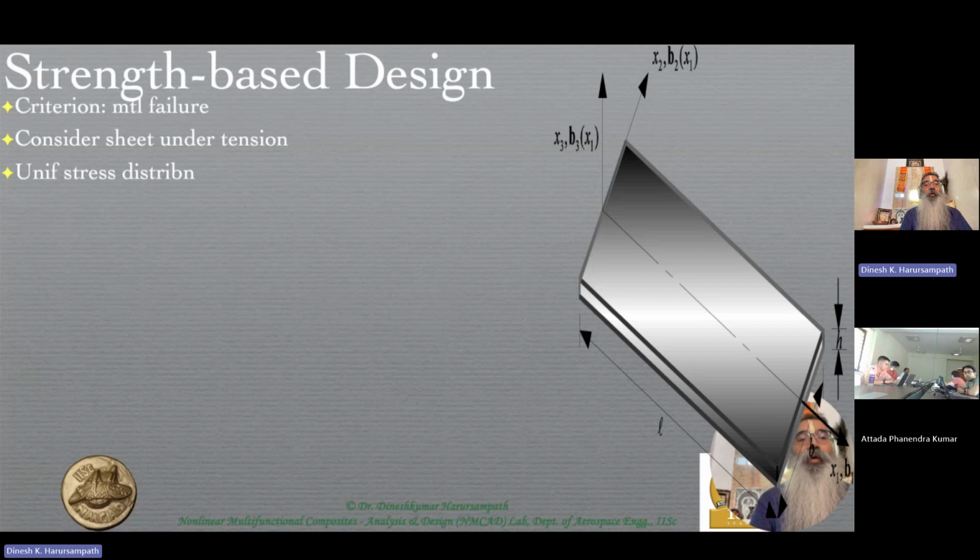And we want to assume that that stress is distributed uniformly. We already invoked a particular principle called Saint Venant's principle to help us out, so that if you go a distance which is of the order of the thickness of this plate, then in the interiors of this plate, it really doesn't matter how exactly you're applying that particular load here. The so-called concentrated load might be applied at x2 and x3 equal to 0, which is the origin at that cross section.